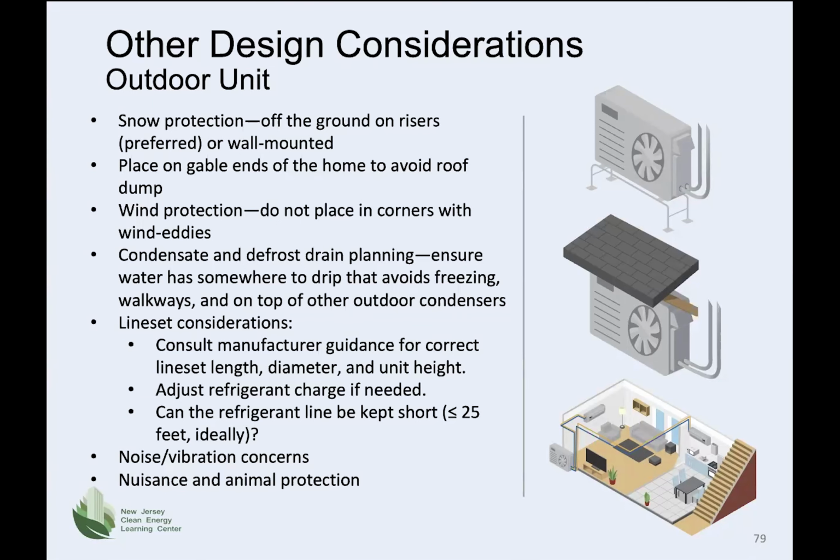The condensate lines, one of the big considerations there is you don't want the condensate to freeze when it's cold outside. Because if the condensate freezes, that's going to be a mess. It could crack the condensate drain piping. If the condensate drain goes onto, say, a walkway, it could be a problem. Sometimes they stack these outside air units one on top of another, and that's probably not a good practice unless you're very sure that you have a good condensate drainage system.